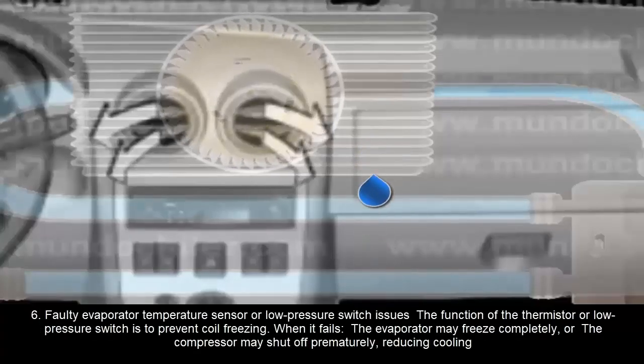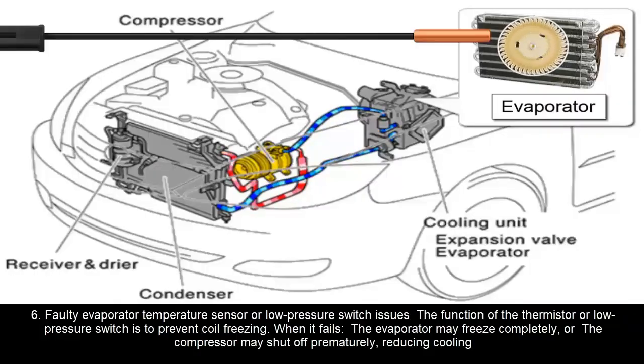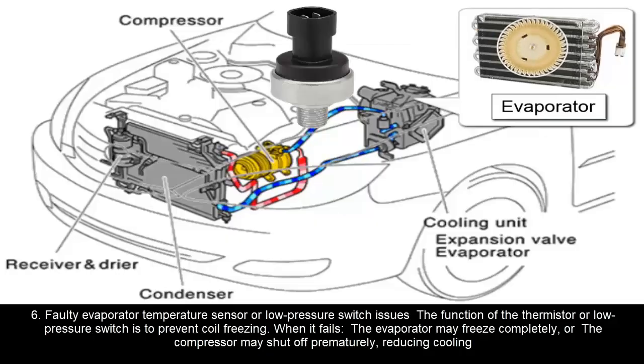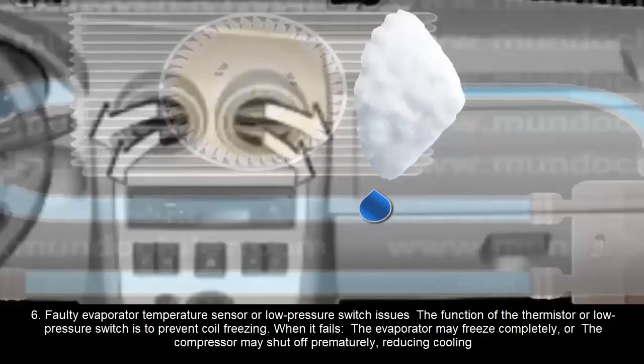6. Faulty evaporator temperature sensor or low-pressure switch issues. The function of the thermistor or low-pressure switch is to prevent coil freezing. When it fails, the evaporator may freeze completely or the compressor may shut off prematurely, reducing cooling.